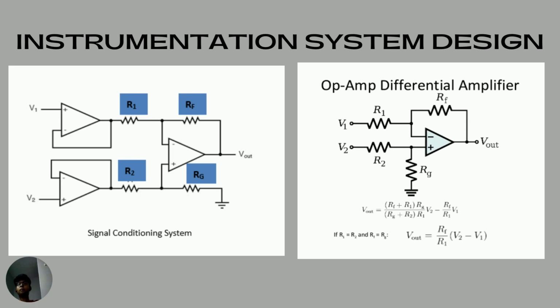It's an op-amp circuit whose output voltage is equal to the input voltage. Hence, a voltage follower op-amp does not amplify the input signal and has a voltage gain of 1. The voltage follower provides no attenuation or amplification. It only buffers the system.